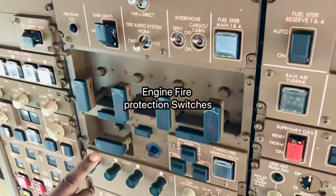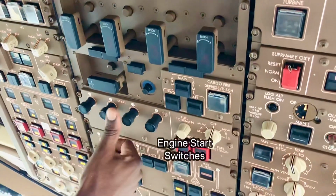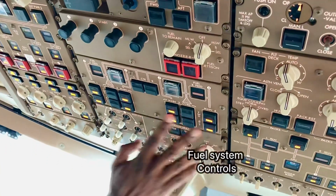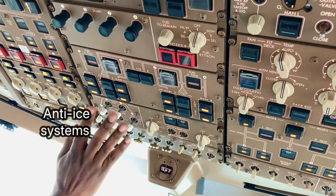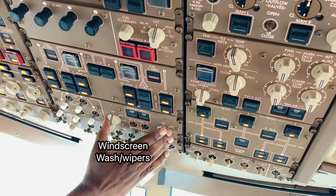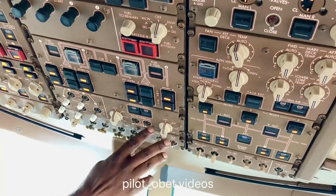All the fire switches are in. APU fire switch is in, start switches are in. Crossfeeds are open for the fuel. Fuel pumps are all off at the moment. These are the lights I expect. Engine anti-ice, wing anti-ice off. Windscreen wash and windshield wipers as well.